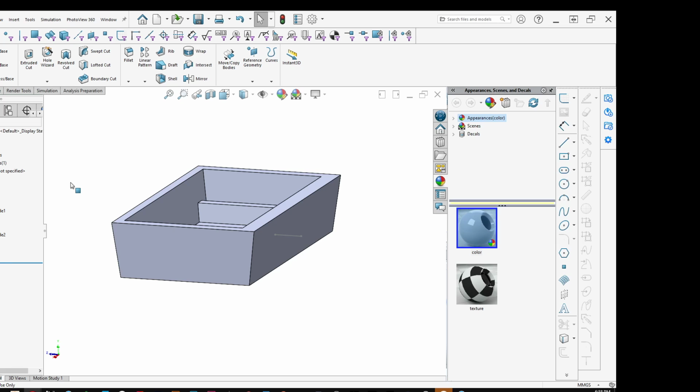The process that you're using. You know, the bigger the wall thickness, the more expensive because you're using more plastic. The more plastic that you're using in the part, the longer it takes for the part to cool on the tooling. And if you push a part off the tool too quick while it's still hot, think about grabbing your 3D print off your printer and it's still hot. You're going to deform that part. And if cycle time is very important, i.e. we've got to have 2 parts per 5 seconds, you've got to accommodate for that.